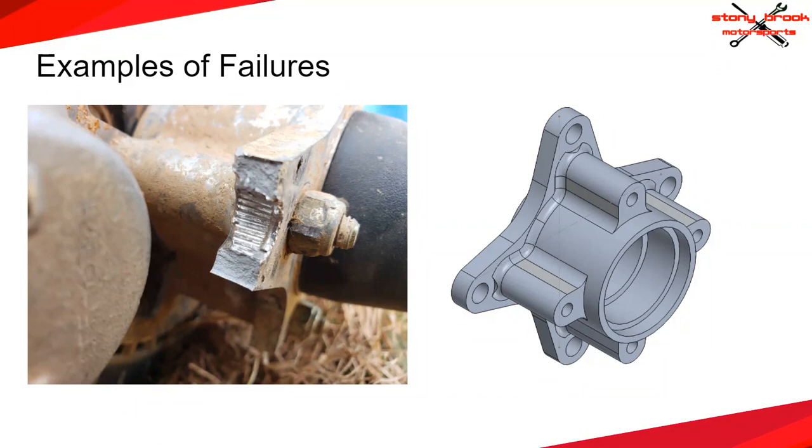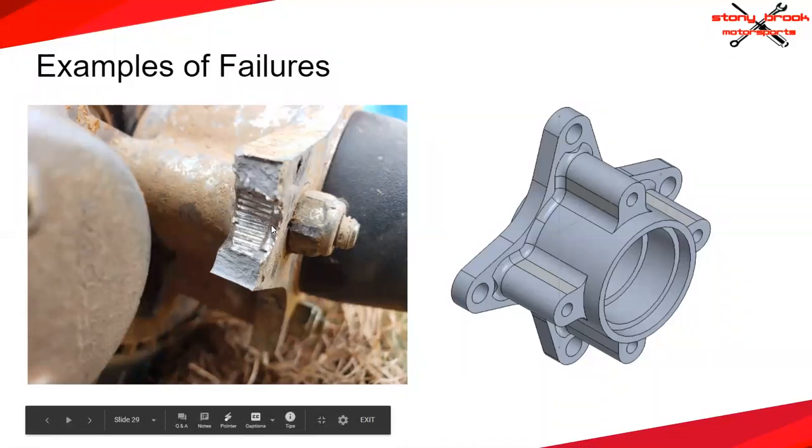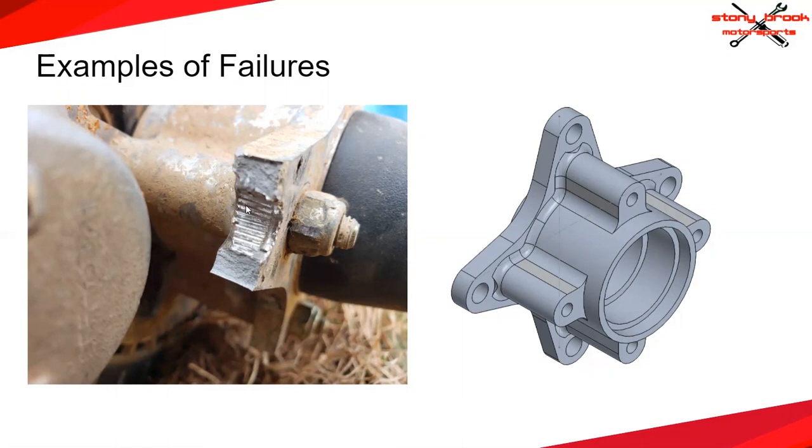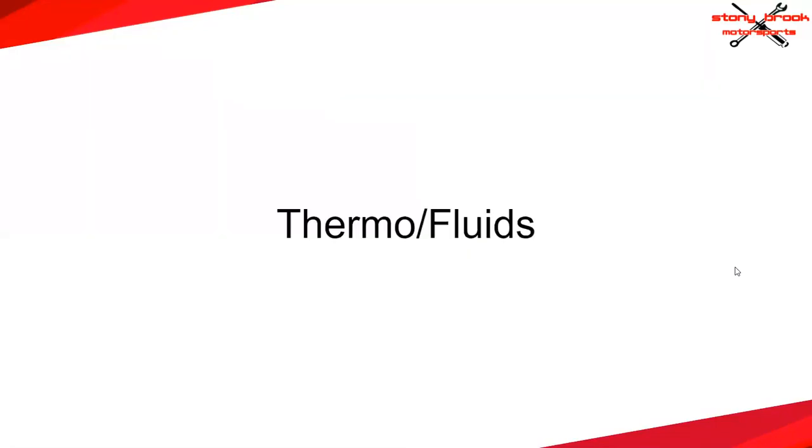So as soon as there was a force on it, in this case the car landing on one tire, it immediately failed. You can see along this edge of the piece that you actually have a lot of buildup of material, and that's because the press fit was literally forcing material through and pushing it to pile up. Long story short, know your press fits. There are standards for it. Not important to discuss now, because those can just be looked up, and we'll go more into details with your systems.